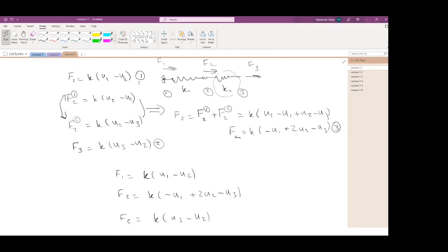And if you want to add the displacement together, this is not going to work. The difference between U1 and U2 is basically the amount the spring is compressed. So the sign convention is completely up to you. I could have assumed that F1 is moving in a different direction and U1 and U2 are moving in different directions. I just need to be consistent in my assumptions. I would suggest, if you want to try it on a different set of assumptions, be consistent throughout, and then you are going to get exactly the same results eventually.